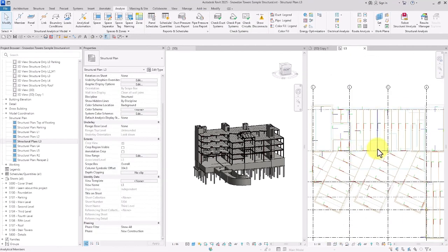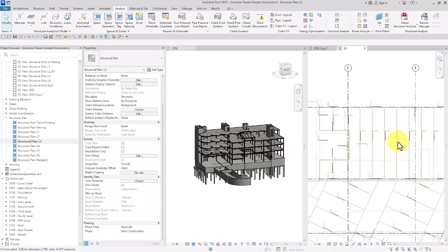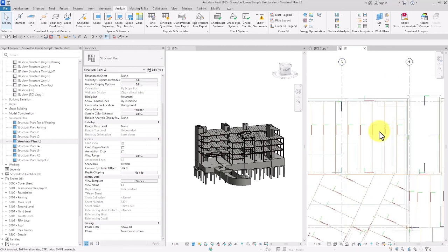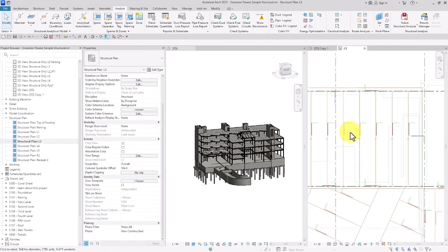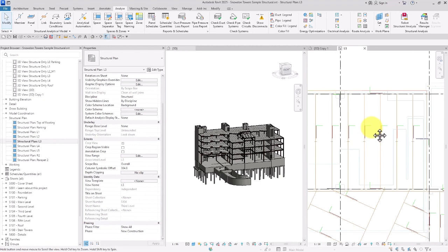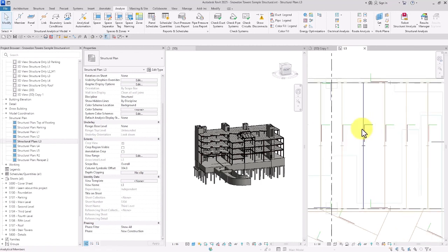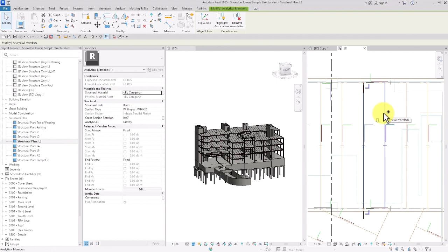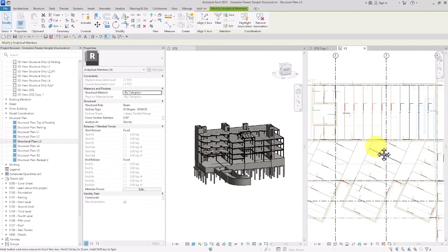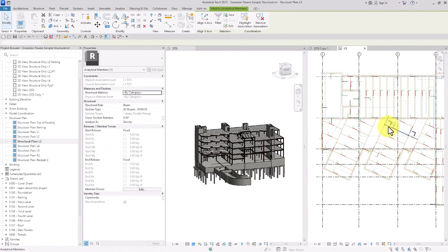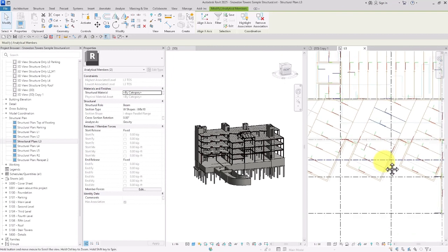Now, if we take a look at the axis, we can actually detect their directions. However, sometimes you might be working with a model containing axes with reverse directions. For example, one of them might be set towards right and another one might be set towards left. So in fact, we can say that there is a lack of consistency between them. However, now you are able to select several analytical lines and then, for example, modify their x-axes simultaneously. This is an extremely useful and nice technique that we can use in our projects with a few clicks.